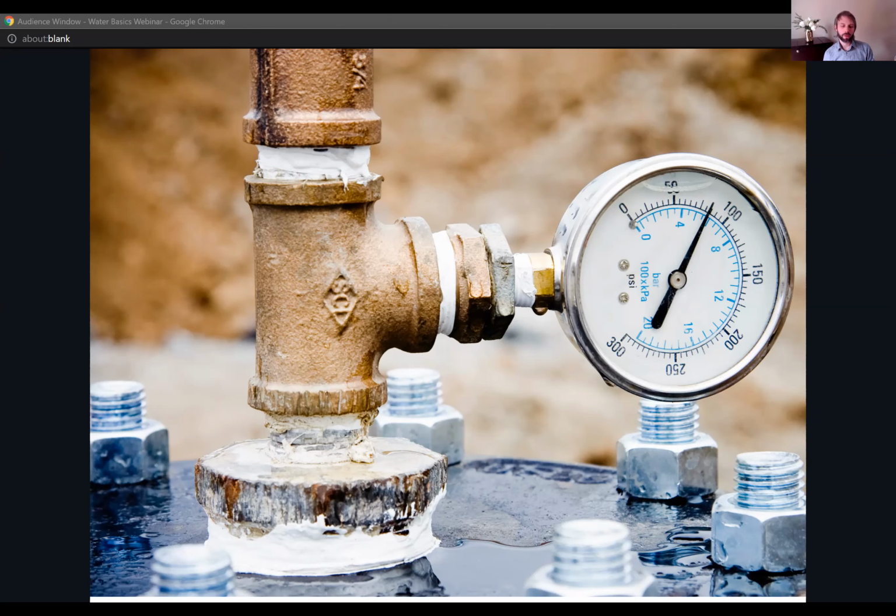So when you're in there doing your testing, go ahead and set one of these pressure devices. You can set it up outside, use a little hose, set it out on the spigot, put the pressure on. When you start your audit, get the pressure initially, and then walk away. Keep the water running. Don't use any water. When you're done with your audit, 30 minutes or an hour later, check the pressure. Did the pressure drop? That might mean there's some leaks going on in the system.